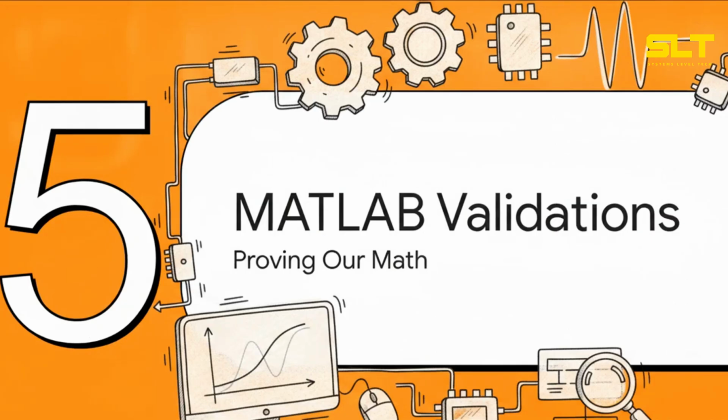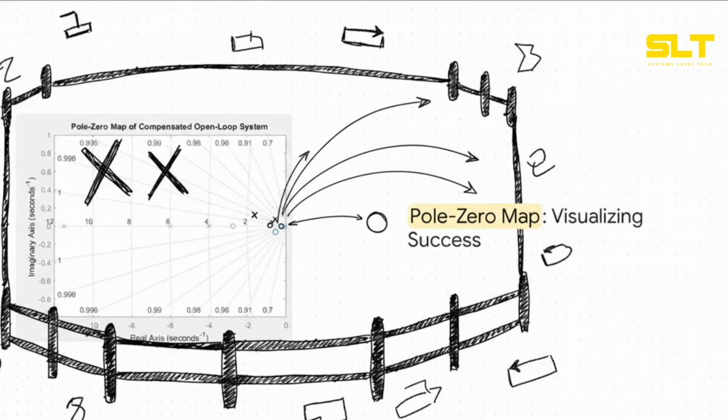Section 5. Validating with MATLAB simulations. Now it's time for the proof. First things first, we generate a pole 0 map in MATLAB using our brand new system. Visually, the x's mark the poles, and the circle marks our 0. This confirms that our calculated pole at negative 11.483 and our 0 at negative 2.755 have successfully dragged the root locus of the entire system exactly through our desired design point. We have perfectly corralled the system's behavior to do exactly what we want.